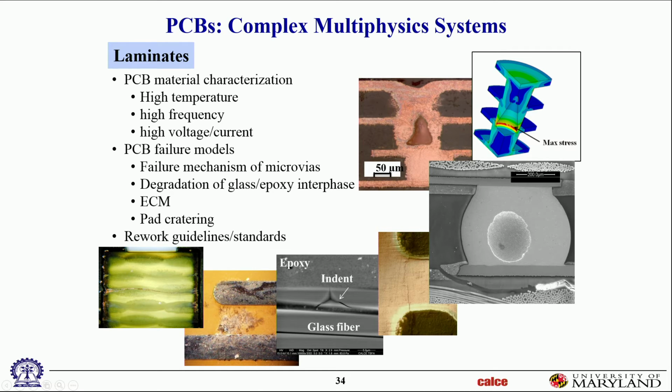Again, this is in the presence of moisture, and of course the circuit card is exposed to moisture. You see lots of moisture on the surface, and there are ionic contaminants from the processing of the printed circuit card. In the presence of all of that, you get rapid dendrite growth when you have a voltage gradient between neighboring traces. It doesn't always happen just between neighboring traces. It can also happen between buried features, not just on the surface. Then we have holes drilled through the circuit card for connection through the thickness. We call the plated holes vias, V-I-A-S. Sometimes dendrites grow from the vias also.